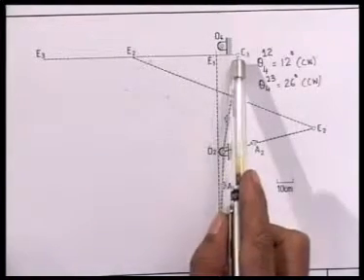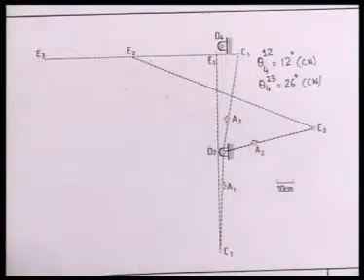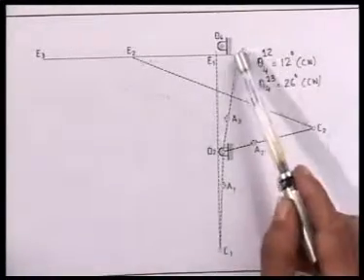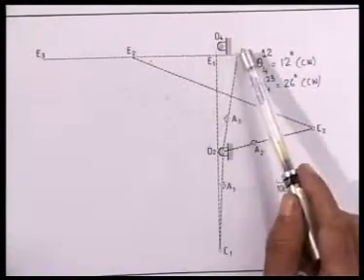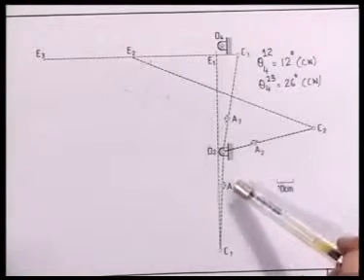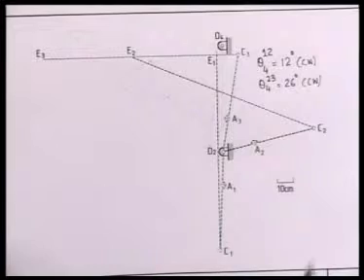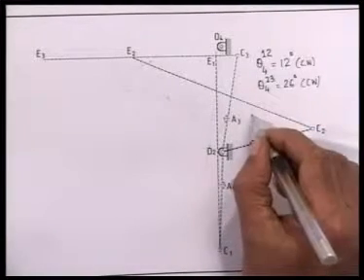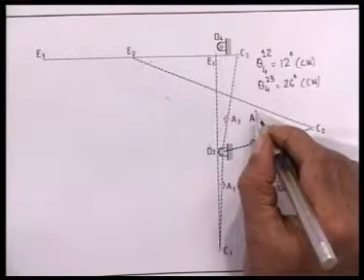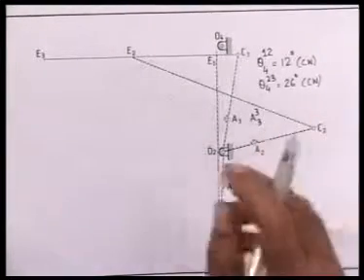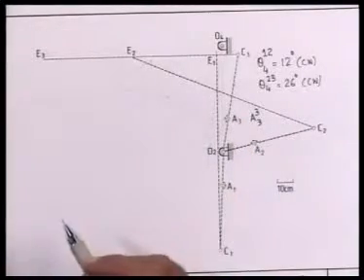Since we have to obtain the position of the hinge B at the third configuration, that is B3, we hold link 4 fixed at its third configuration and make a kinematic inversion and determine the inverted positions of A1 and A2. A3 is nothing but A33, because we are holding link 4, that is O4B, fixed at its third configuration.